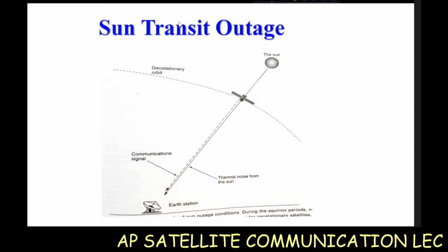And as the day progresses and approaches, say, noon time, the sun is gradually overhead. At some point, as you look up, the sun may directly pass through the line joining you and the sun. That is why it becomes difficult and is not advisable to look at the sun. A similar situation also happens in the case of an earth station antenna. That is, at certain periods of time, the sun may pass directly through the primary beam of an earth station antenna. And the sun is a source of noise and radiation at different wavelengths, including microwave wavelengths, microwave